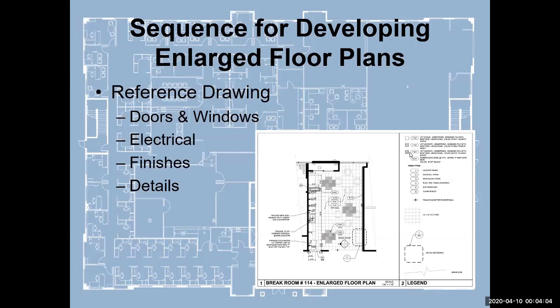So the floor finishes are called out here, they're referenced here, and then you can see by symbol and by color, they're provided there. You can see we've made the call out down here, and we've said that they're typical unless noted otherwise. Okay, and then here's the typical symbol that we would use for those.